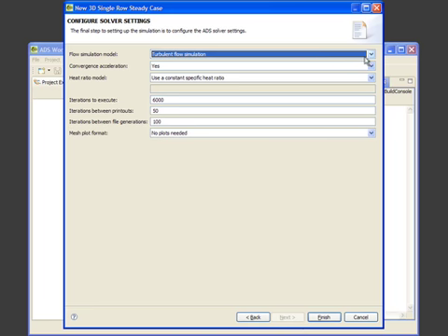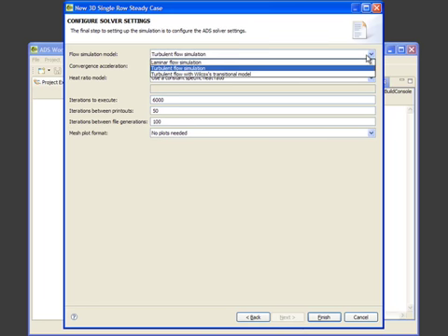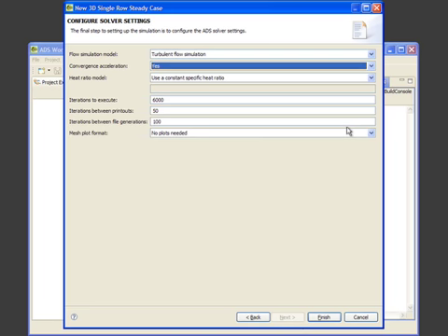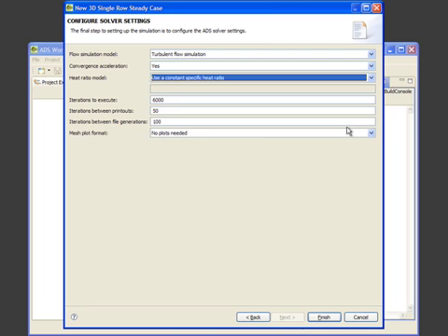Now Leo, the flow solver, also has some settings. You have some flow simulation models that you can use, and turbulent flow simulation is the one we recommend. Always use flow convergence acceleration. There really is no point to not use it. So if we go down, we see that there is the iterations to execute. This will determine the total time that the simulation takes.